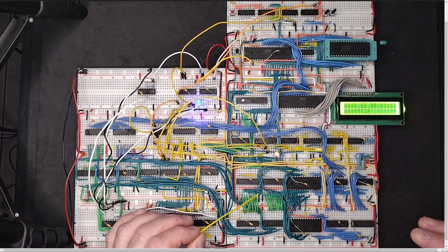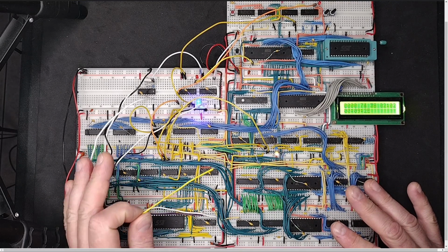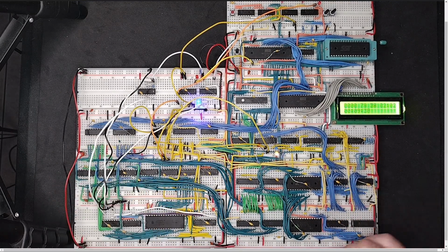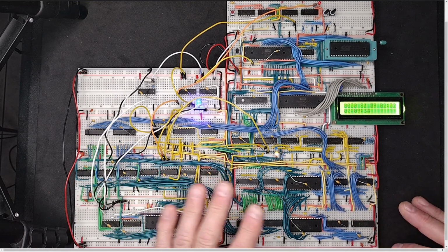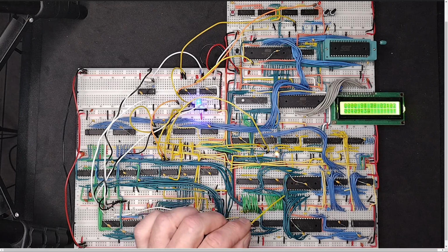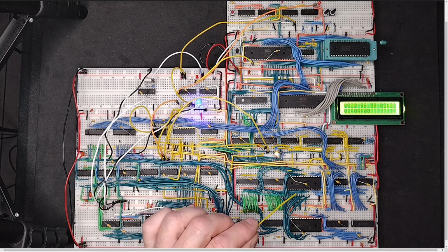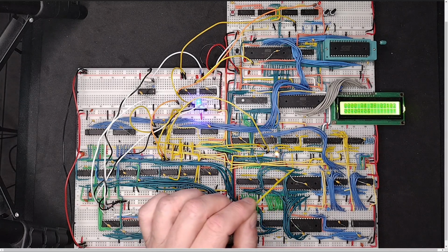What I want to do is to have it so that background RAM scrolls when I change these hardware registers that change these adders, so that I can scroll the background RAM vertically and horizontally. And I want the foreground RAM to stay where it is. But the way I've got this wired right now, I have all the address lines wired between the background RAM and the foreground RAM, meaning they're both using the same set of addresses.